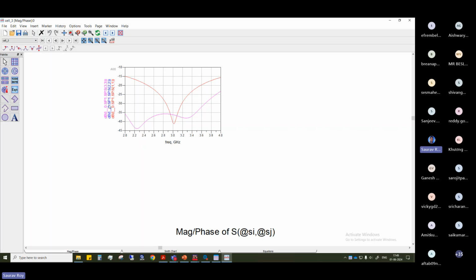As well as, if you see in the result section here, you see how it is different. It shows IO.SP1. Why do all these things come here? It's like in object oriented programming, where you have a dot, which means a structured thing, right? So here also, why is it structured? Because first we started from schematic, then went to the layout, and these layout results are imported again to schematic. That's why all these things have a dot. Actually, it tells that the 3D EM results have been incorporated into the schematic simulation. So that is why this kind of thing will come here.